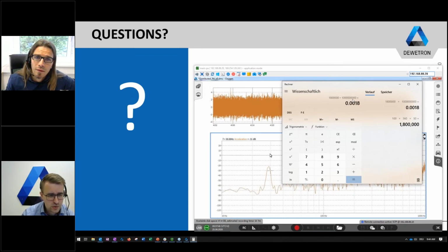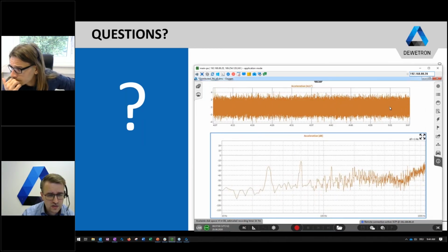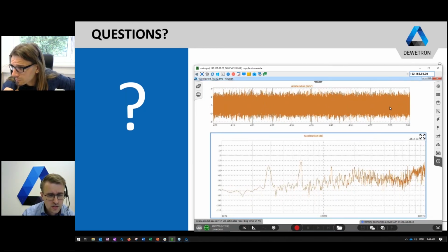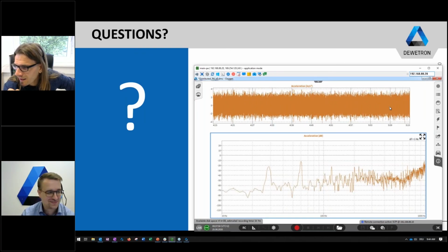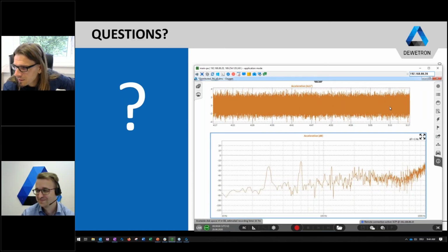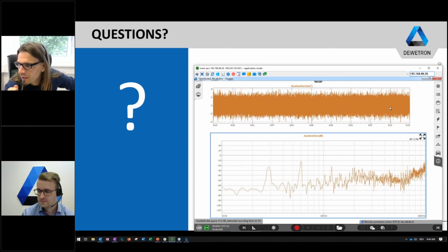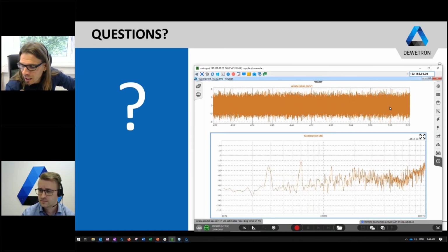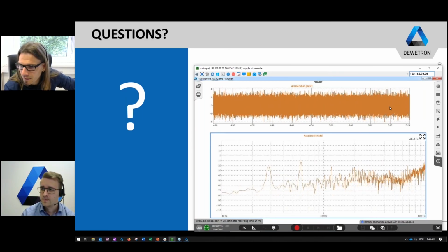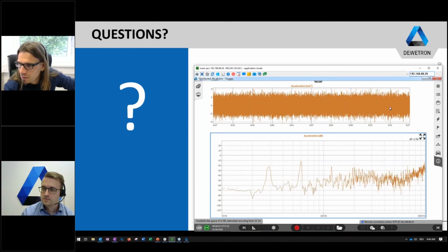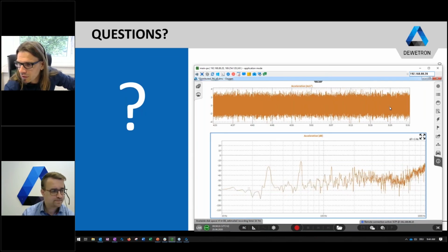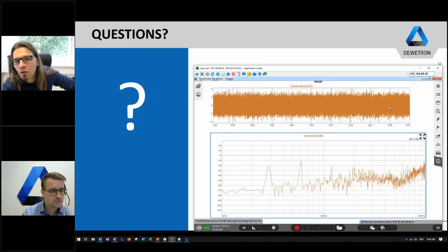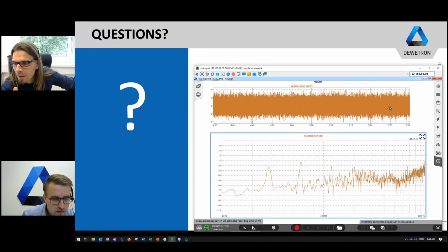Additional to that, the question was also asked, what external hardware is necessary to sync two Tevatron systems? Syncing additional hardware is always a pain. When you only use Tevatron equipment, you don't need additional external hardware, because the Tevatron devices have an integrated timing source, and this timing signal can be output to clock several Tevatron measurement devices.